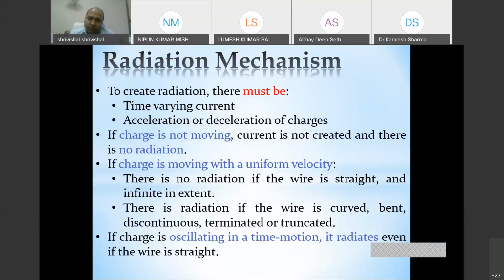If you look at the basic structures, whenever there is a bend or curve, we will observe this if we simulate any antenna structure in any simulator, like CST, HFSS, FEKO, ADS or any other you have used. If you explore the surface current density, you will observe that at those bends and curves there is a change in the current paths. You can very easily verify these concepts.